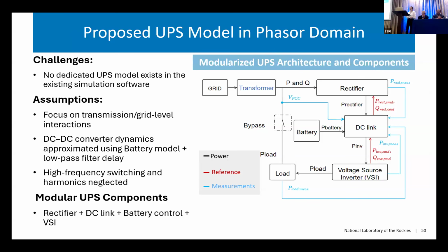So this will provide us the module for the rectifier, and it goes to what we call the battery part. It's through the DC link, and also goes to the voltage source inverters that are performing the power supplies for our downstream IT load.